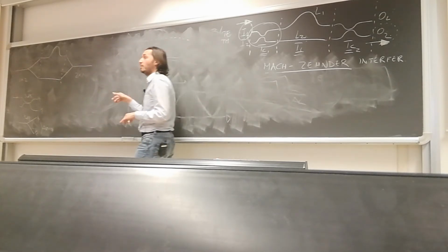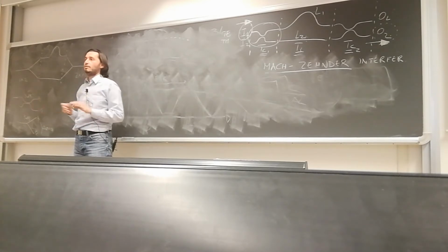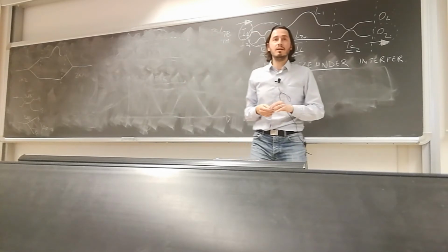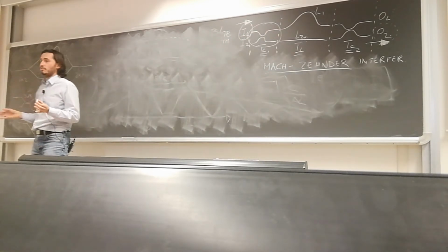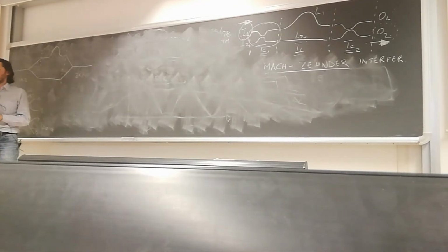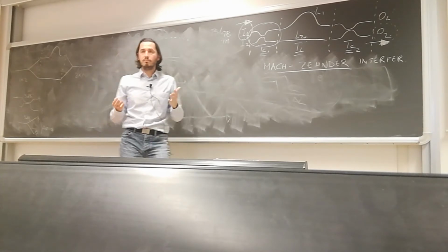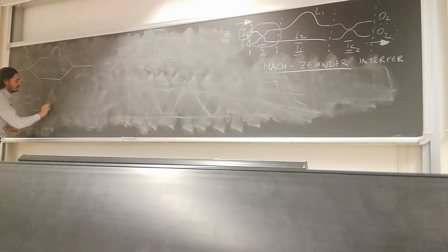Is the same in a directional coupler? Depends. Good answer, depends. Okay, if I have a 3 dB synchronous directional coupler, the most simple that you can imagine, the phase shift is, they are in quadrature, okay? So this delta phi is pi half.